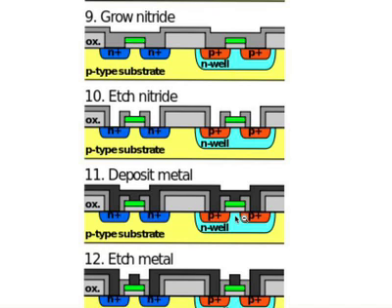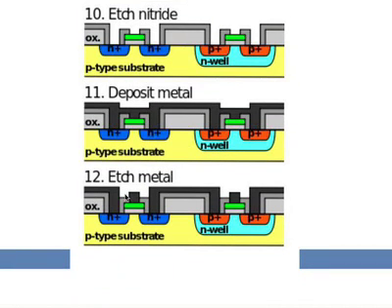So this is your inverter, by the way. That is the device that I showed you 2 slides ago, that you see here because they're connected in series. Then you etch the metal so you can separate the source, gate, the source, gate, drain. These 2 drains are connected together. Okay, this is our inverter circuit, pretty much. This is the output terminal. The input terminal are the gates. This goes to VDD. This goes to ground. Right? That's how you make the inverter.